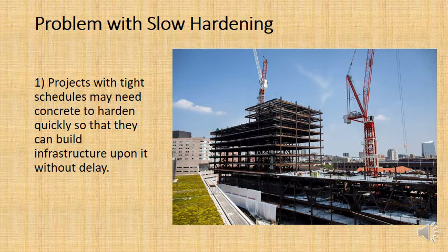Look at this high-rise they're building here. I think it's a high-rise car park. Now, they're building on top of a concrete platform. They're not going to be able to build a new level to that high-rise car park until the concrete underneath it has hardened and reached a strength appropriate for the design. And so that creates delays.